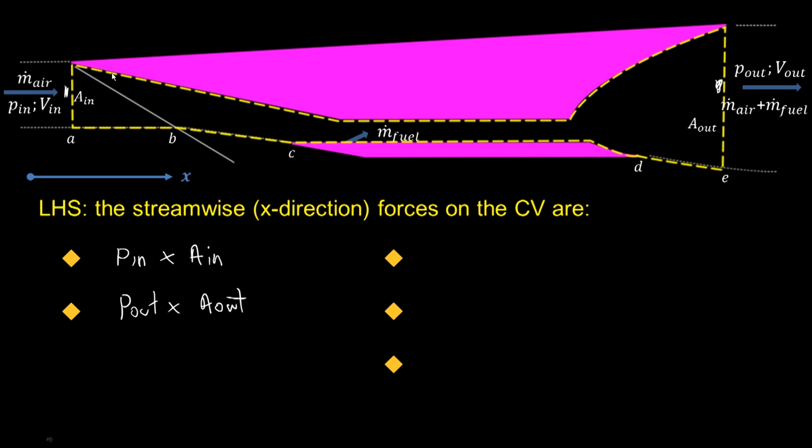Many of the other surfaces of the control volume are the ones we are interested in that contribute to our thrust, and I'm drawing on some of them here. So all the surfaces where the control volume is in fact touching the inside of our scramjet flow path, all those forces will contribute to the thrust that the scramjet engine supplies to the vehicle.